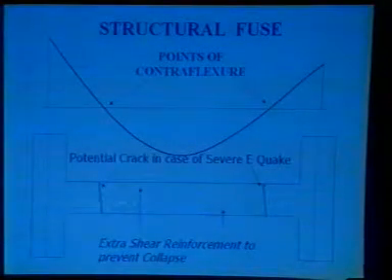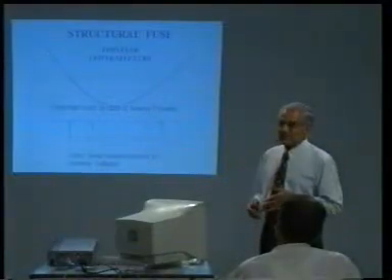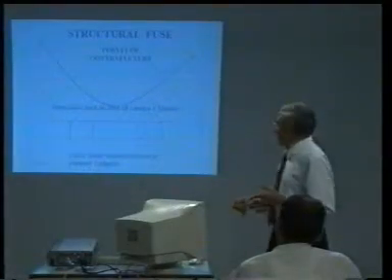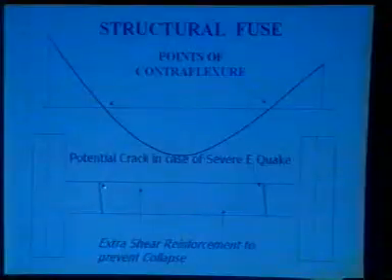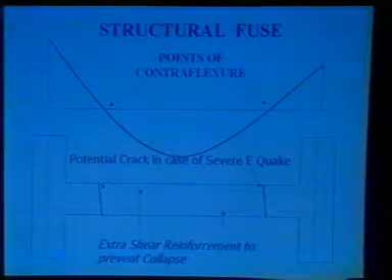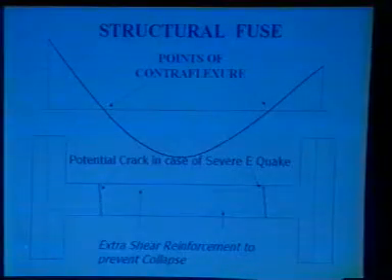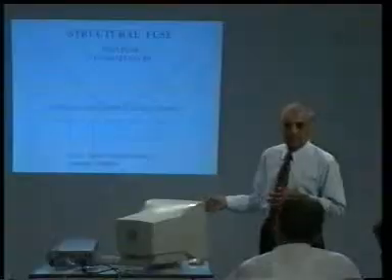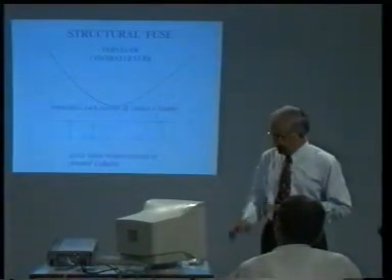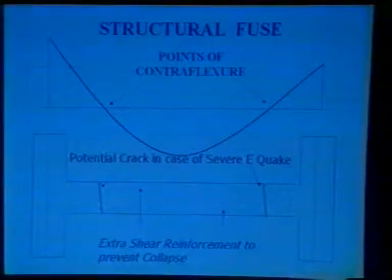So, this extra reinforcement is not going to provide any moment resistance, but at the same time is going to provide a heavy amount of extra shear resistance to the structure, with the result that when an earthquake takes place, this part will crack up and relieve the stresses from that place, but will not at the same time allow this panel to fall down. When this panel does not fall down, a major amount of damage has been saved and loss of life can be highly minimized. After the earthquake, you can always repair this and put the structure back to use.